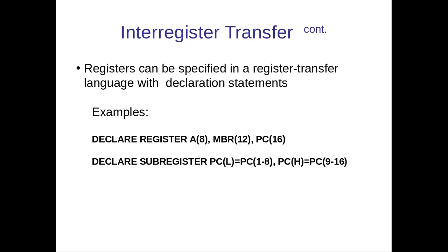That is, we can specify our digital system in a very high level language, register transfer logic, and then it can be translated into a low level circuit, at the register or transistor level, with the help of special compilers. And that object file can be given to a fabrication lab, and then we can fabricate our ICs. That is the advantage of register transfer logic or register transfer language.